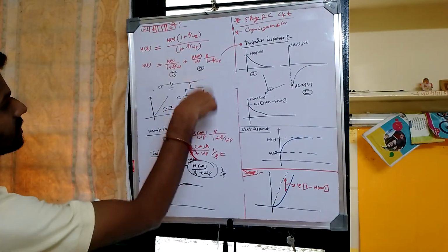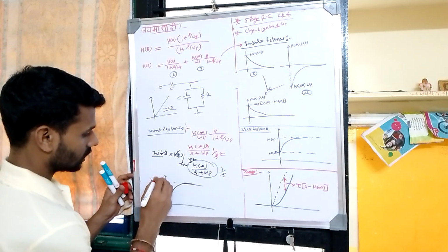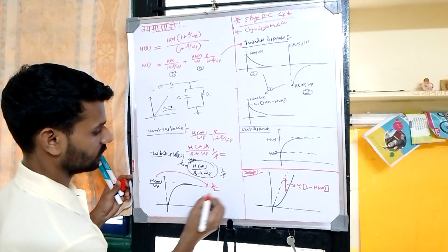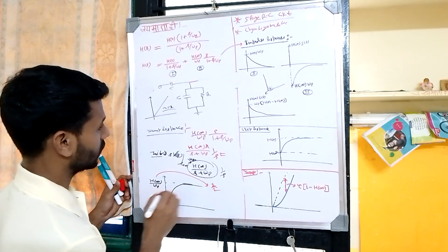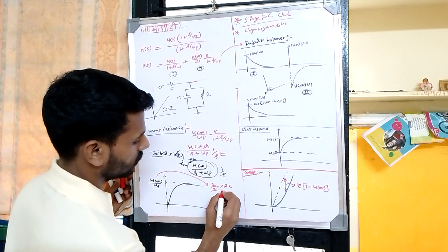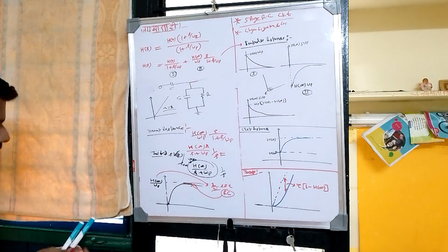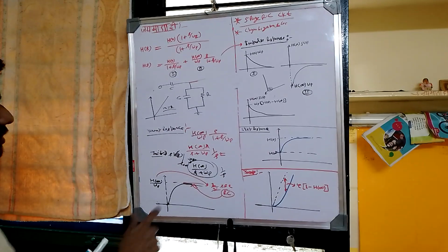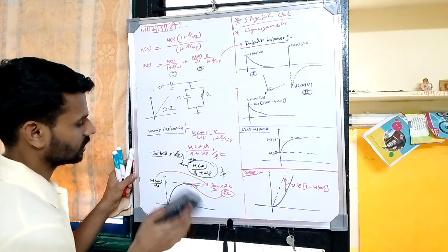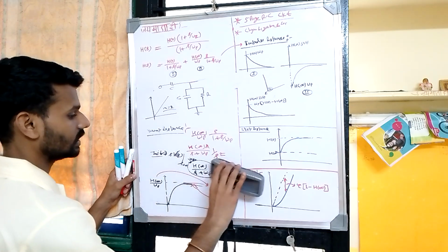So for this circuit, your ramp response will be this. And if you calculate H of infinity, I already discussed in the last video, H of infinity will be 1 by 2, and omega p for this circuit is 1 by 2RC, so the 2 will cancel and it is RC. This is the final value. So your ramp response for the circuit looks like this. You calculate this using Laplace, KVL and KCL, but I also want to discuss it by intuition.